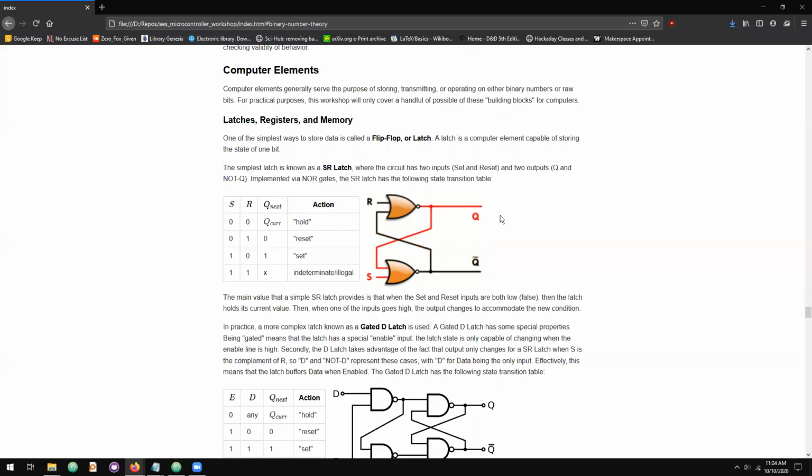The way I can represent this is called an SR latch. It's a combination of digital logic gates where you can represent the output value as, again, a function of the inputs, but there is a state in which the output doesn't change. And that's how we end up getting our value storage.